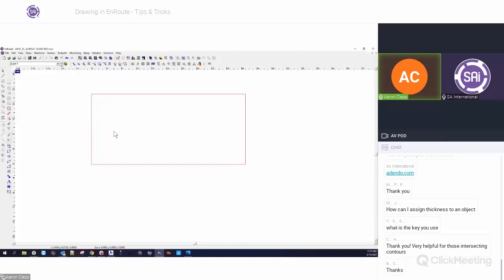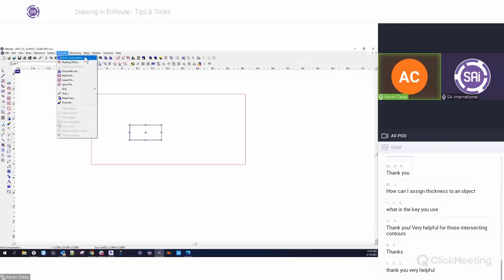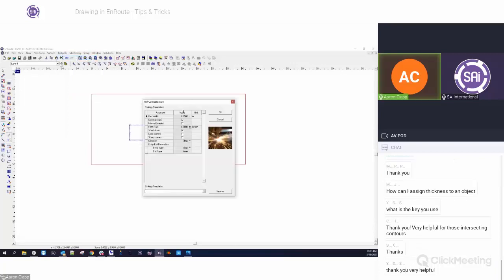Okay, I think we've got two more questions. John just had a follow-up when we were asking about training. You wanted to know what section would you read that pertains to plasma cutting? So if you're doing anything with plasma cutting, typically you're going to read up on the sections for your kerf compensation. So kerf compensation is the toolpath that's all about plasma and water jets and stuff like that. So the kerf compensation section would be the area that you'd use for the plasma sections.